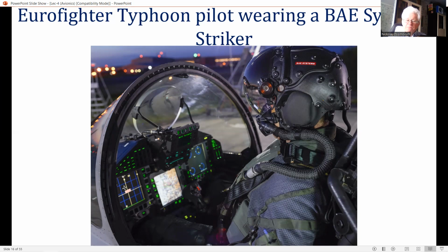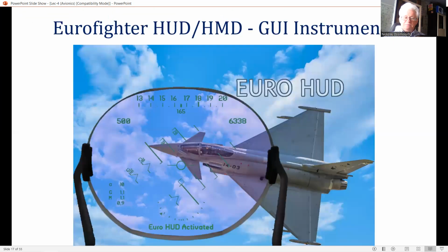The advent of a practical eye tracker may eventually improve the operational accuracy of the HMD. A further difficulty with the HMD is that it is not easy to compensate for windshield error to a very high degree of accuracy over the whole head motion box. The end-to-end accuracy chain for the HMD will, in addition to the HUD factors, have three additional factors: helmet alignment, tracker accuracy, and windshield.